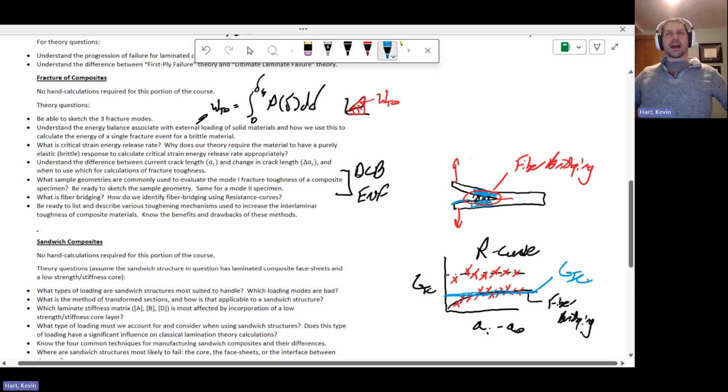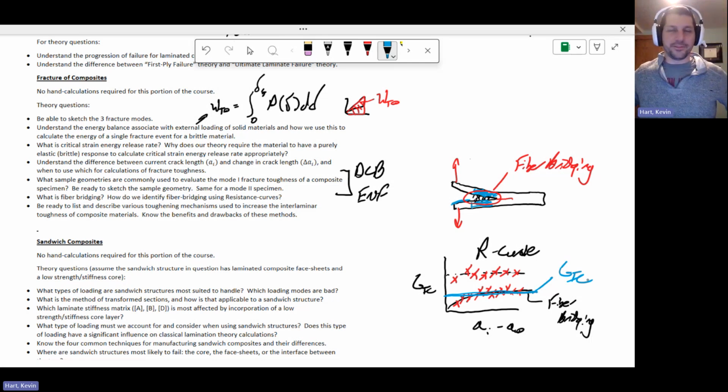When you actually manufacture a composite, there's not going to be any film, any pre-crack region built into that, hopefully. That pre-crack region and that R curve is specifically just an artifact of making those specific double cantilever beam specimens. So the true G1C value is the value that you get after that equilibrium has been reached between new fibers appearing and old fibers that are hanging on breaking, right? So that's what happens there.